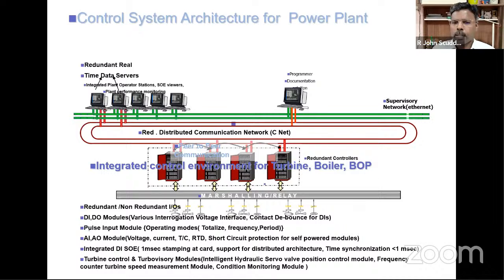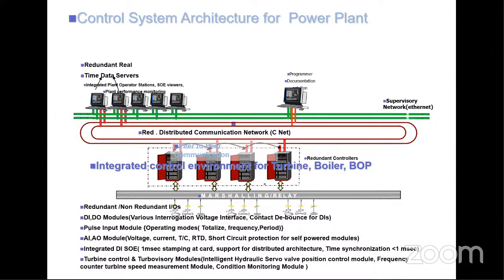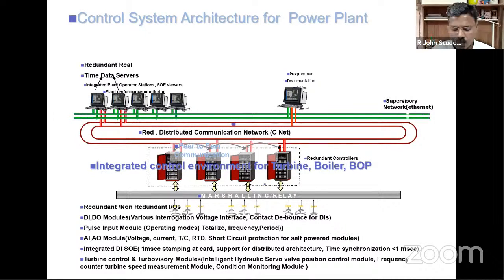So ideally, there is no breaking in the communication or control network. Imagine before this lube oil pressure low happened, the pump has tripped. Now, what has caused the lube oil pressure low? That you will not know. So in that case, the pump tripping would have come as the first input, followed by the lube oil pressure low. Then you will understand the pump which has tripped first is the actual root cause of the tripping of the turbine. That is what I meant by first out logic or sequence of events logic.